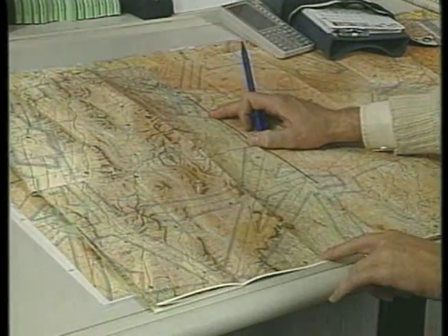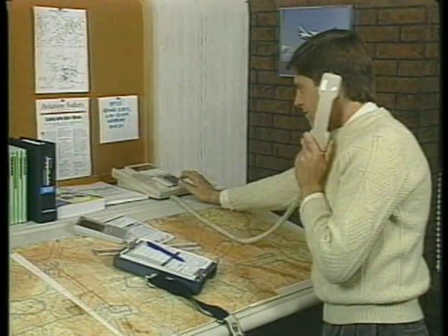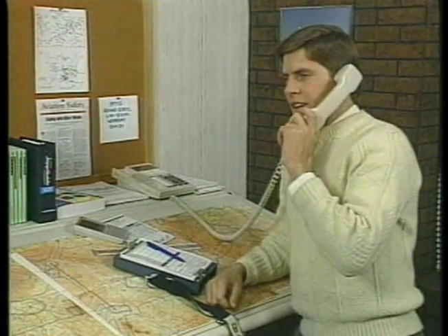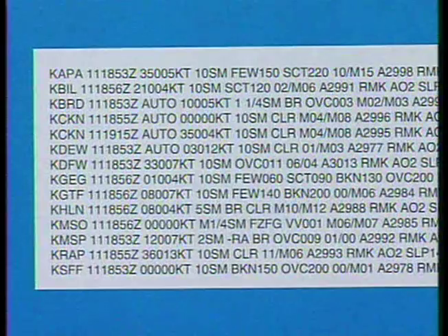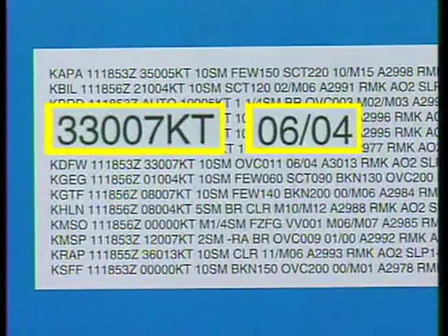Your preparation for a night flight should also include a complete weather briefing, including a study of the available weather reports and forecasts. When reviewing this material, it is important that you pay close attention to the temperature dew point spread. A small spread is a good indication of the possibility of the formation of ground fog. Because aircraft drift is very difficult to detect during takeoffs and landings at night, it's a good idea to also pay close attention to the wind direction and speed.